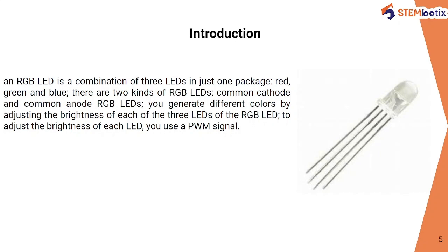However, LEDs and LCDs are only capable of displaying those colors individually. These LEDs can be mixed to show different intensities of these three colors. Because of the small size of each LED, your eyes are tricked into seeing a different color that isn't actually there, with the Arduino and a technique called PWM. The full form of PWM is pulse width modulation. We can pulse each color of the LED separately to create many different colors.